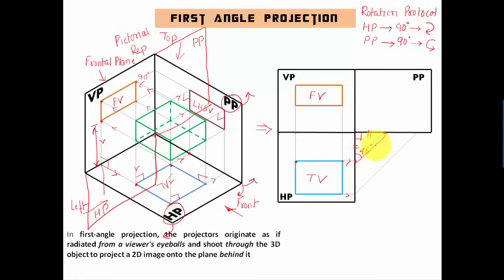That's it. And you're going to go ahead in the upward direction. Finally, you have to draw projector lines from these points, something like this, and it's going to look something like this. And finally, these are the intersection points that you're going to get. And when all these points are joined in proper sequence, you have a view. And since you're looking at this object from the left hand side, you're going to have a left hand side view. So let us summarize all of these things, guys.